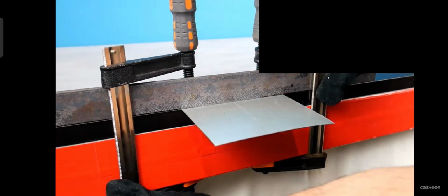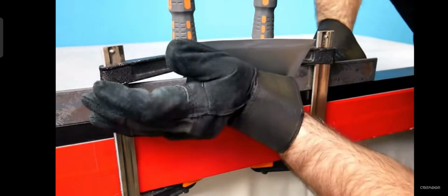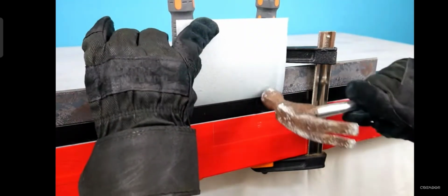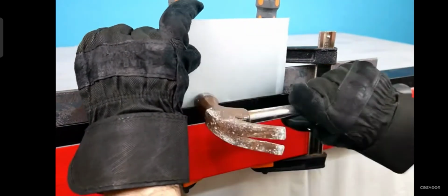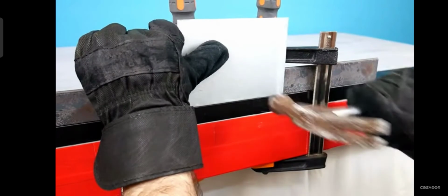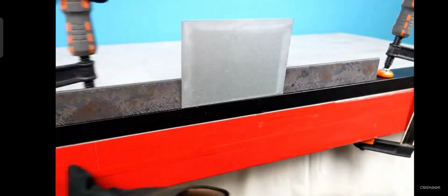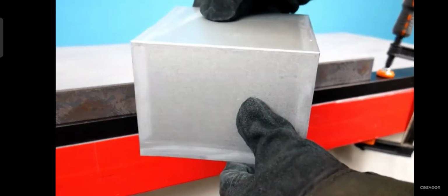Method number 2, with a hammer. With everything clamped, I give a good push by hand like the first method. Then on the bend, I give it a soft hammer, slowly refining the edge, moving along the bend, trying to keep the hammer hits as tidy as possible. It has a few dents in it here and there, but it's definitely a tight edge.